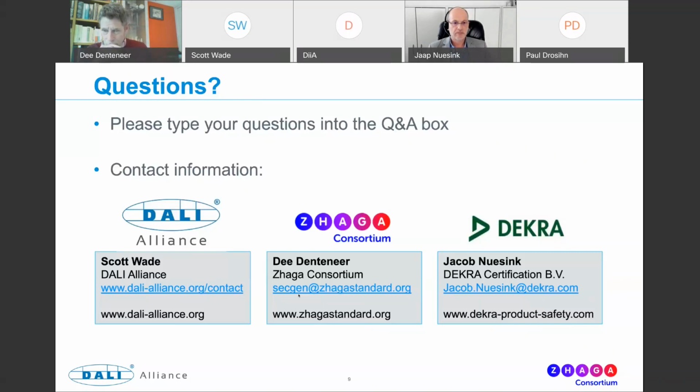So if you're developing or designing an installation, you select the drivers or luminaires that provide the features that you need. In our product database, you can see exactly what you're getting for each product, which parts of the standard are implemented. If you need energy and power, that's part 252, just select that. And then you'll find all drivers, whether they're D4i or DALI 2, that implement the energy and power part of the standard. So I don't see any danger there. It's quite clear what you're going to get. Okay.